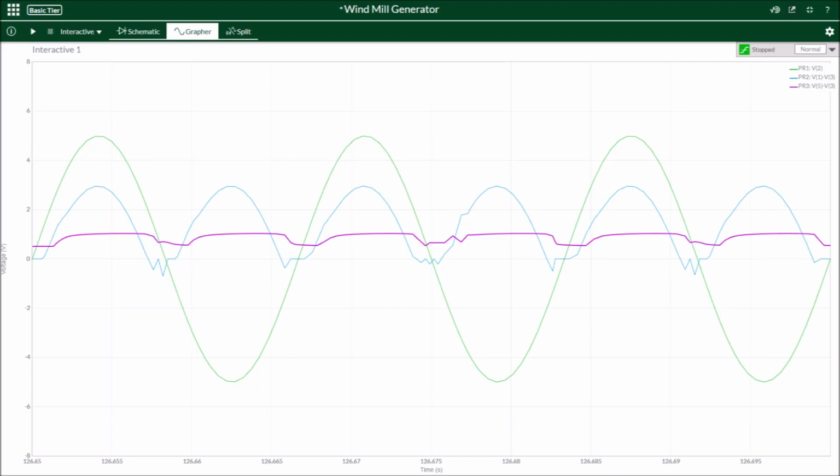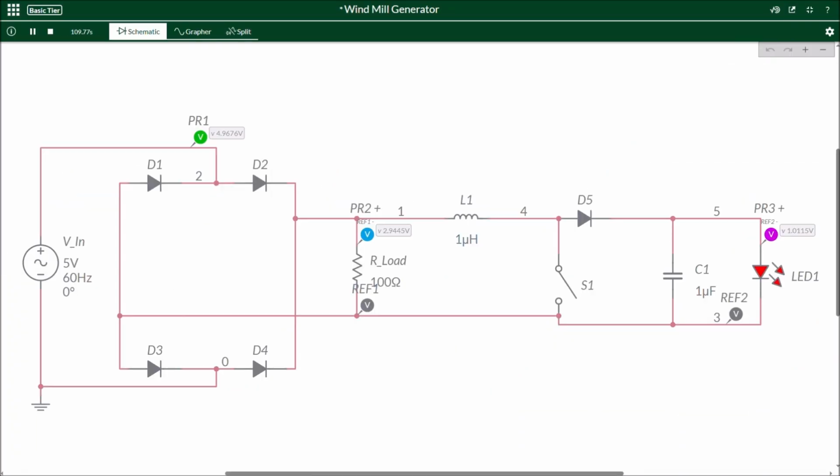Now the limitations are that it has a very low power output, it has no voltage regulation, and of course a small capacitor for storage, which is not very efficient. The LED brightness depends heavily on input voltage, so the LED may flicker, and even dim at certain instances. Also, there is no protection against overvoltage or fluctuations.